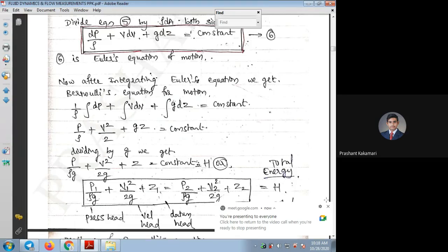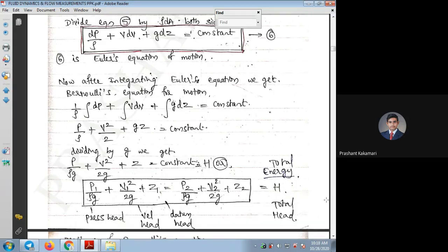So this equation will be very helpful for many topics later in fluid dynamics. We are using this equation many times as our reference to find any energy or head at any given points, or also if the continuity equation is not enough, or in the continuity equation we cannot substitute velocity to find the discharge or area. In such cases we can go by the energy also.